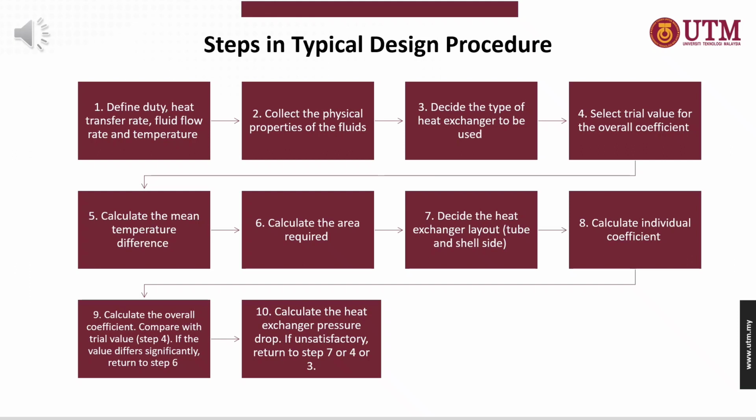Compare with the trial value, step 4. If the value differs significantly, return to step 6. Next, calculate the heat exchanger pressure drop. If unsatisfactory, return to step 7 or 4 or 3.